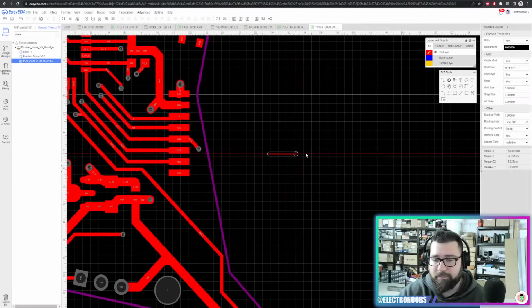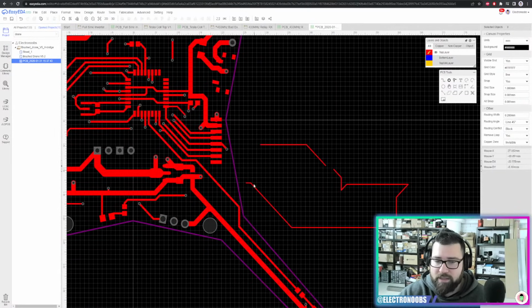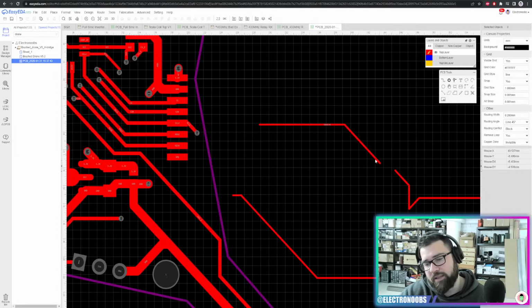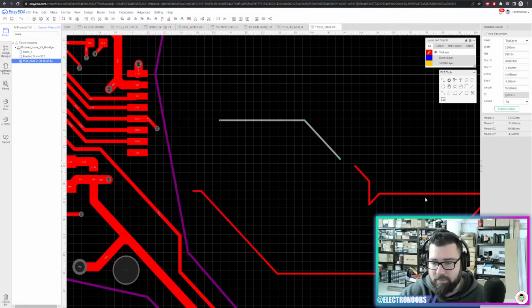Also, when you want to have very synchronous signals, for example, if you have a track like this connected from here to here. Sorry, let me just change it back to 45. So imagine that you have a track like this, and you have another signal that's exiting, I don't know, from here, and it goes like this, like this, like this, to this point. You want these signals to get here at the exact same time, and also to have the same resistance, so you need to make these tracks the same length as this one.